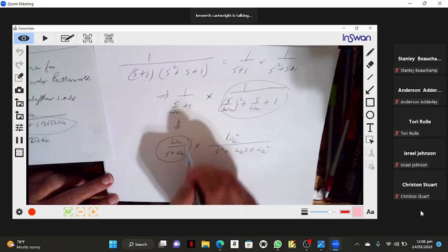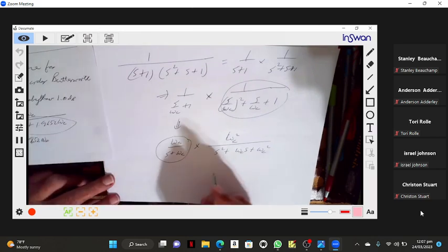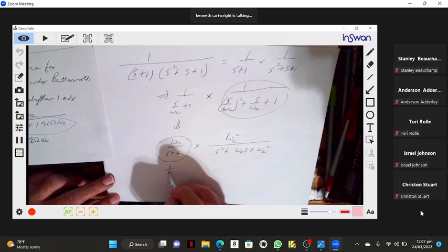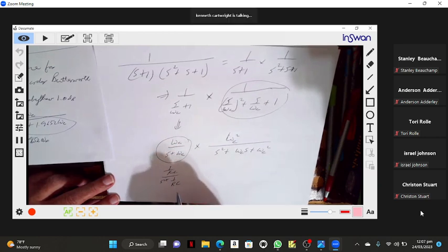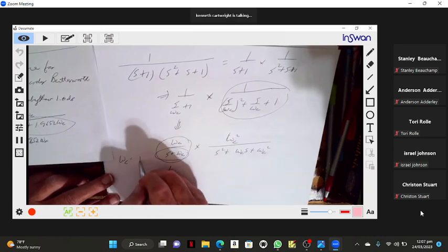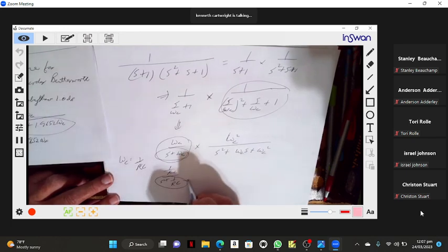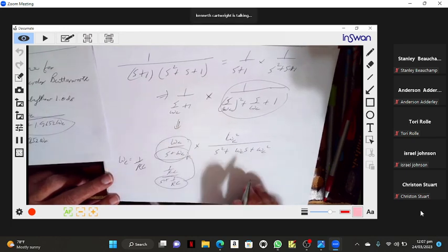Now this part, some of y'all didn't even give me. Y'all didn't even give me the design of the first order. Well, I'm not saying all of you didn't, because I haven't seen all of you. But this is 1 over RC over S plus 1 over RC. And because this has to be this, omega C is 1 over RC for the first order. That must be true.